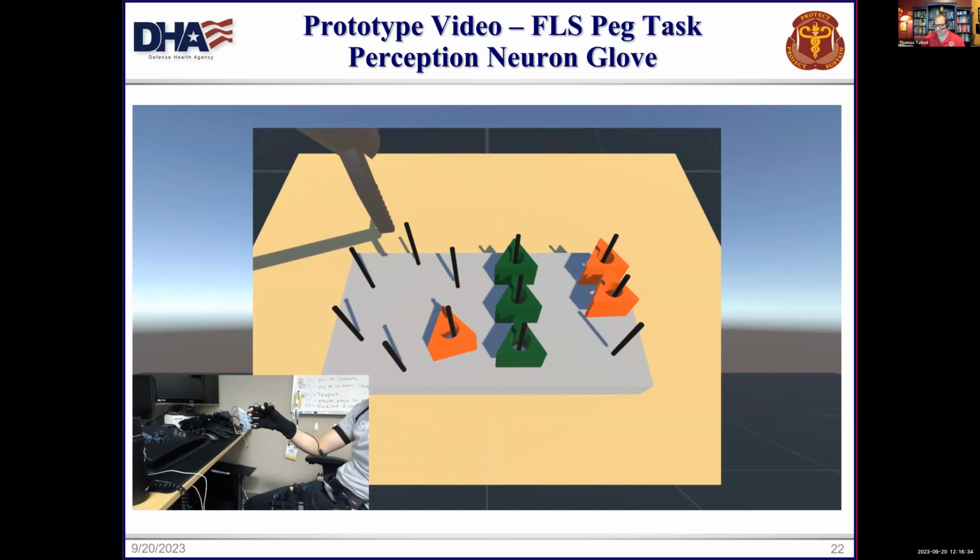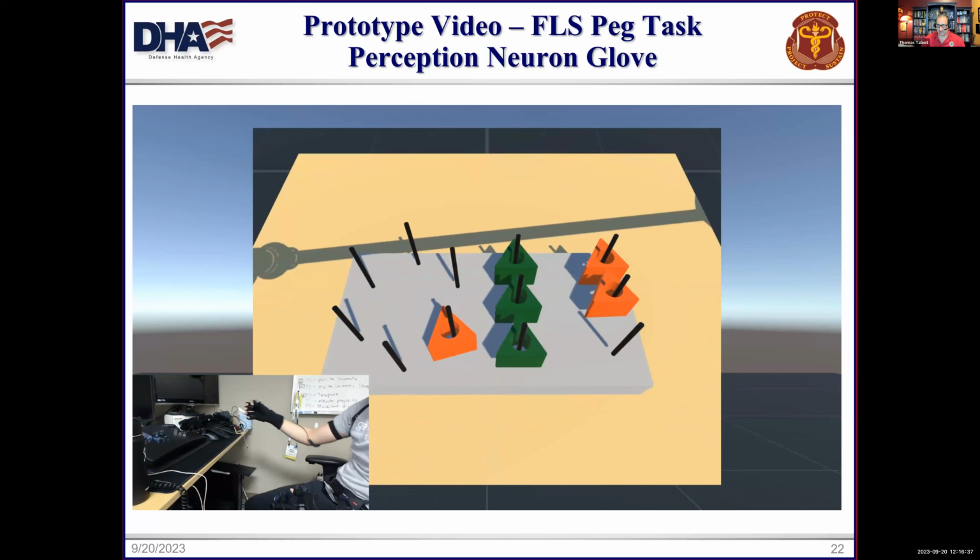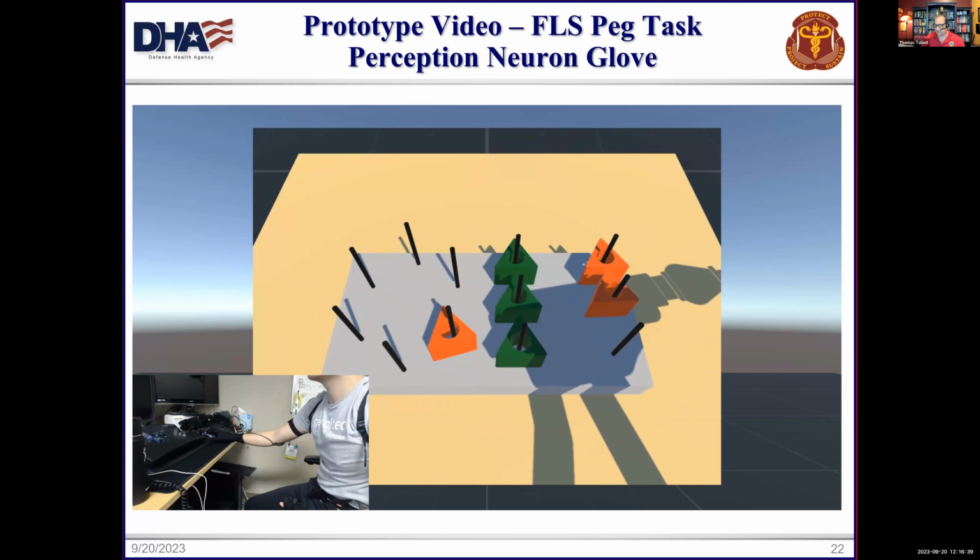The advantage of gloves is that you never lose track of how the fingers are positioned and what they're actuating. But the disadvantage is their absolute position in space and orientation drifts over time. So optical gets the absolute position and doesn't drift, but sometimes you block part of the hands or the fingers, whereas the gloves never lose track of what the fingers are doing, but the absolute position can go off over time. We found that combining a glove and the optical works best because it's almost infallible at that point. You get a perfect interpretation if you combine both sensor modalities.